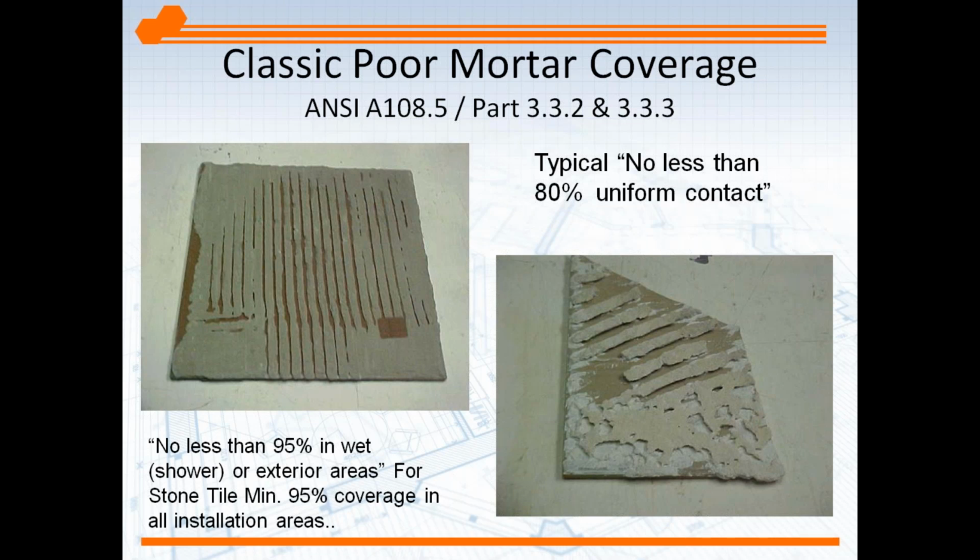Also, on the 95%, that's for all stone. Stone is 95% as well. They don't have the 80% standard in dry for stone. For stone tile, it's wet, dry, inside, outside, 95% coverage.